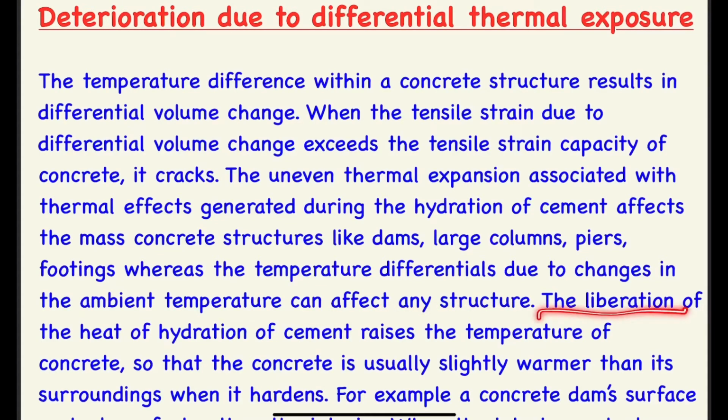The liberation of heat of hydration of cement raises the temperature of concrete. As you know, there is a water cement reaction when cement is mixed with water, so we generally call it heat of hydration. So when this happens, the temperature of the concrete rises, so that concrete is usually slightly warmer than its surroundings.